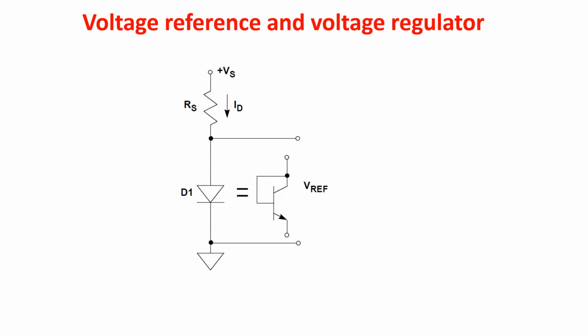Here you see the simplest voltage reference, composed of a diode and a resistor, providing a 0.7 volt reference. This type is also called a shunt-type regulator. Although the reference is decoupled from the raw supply, it has many deficiencies. Among them, the load current must always be lower than the driving current ID. The other important limitation is the negative thermal coefficient of the PN junction.